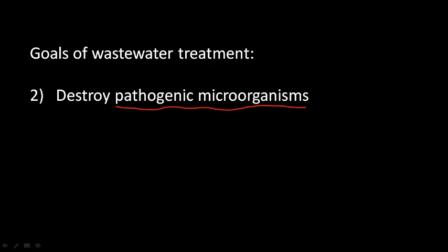We talked at the beginning about why we want to get rid of pathogenic microorganisms from our water. Over 90% of the bacteria, viruses, or parasites present in water will get trapped during flocculation, and they can then be removed from the clarified effluent. But pathogens in particular are on the losing end of a numbers game. They're usually outcompeted for limited resources. They get eaten by other types of microbes. And even if that isn't enough, the clarified effluent, or the secondary effluent, gets disinfected before it's released from the plant, and we'll talk about how that's done in a little bit.